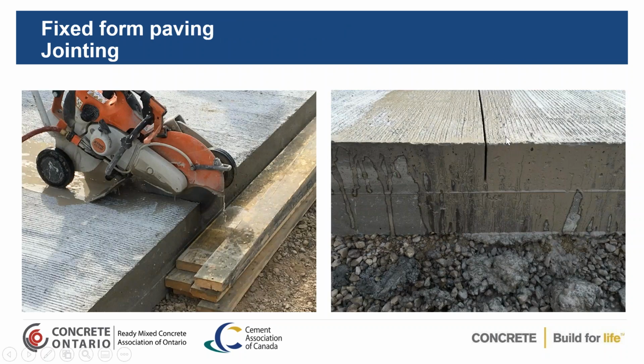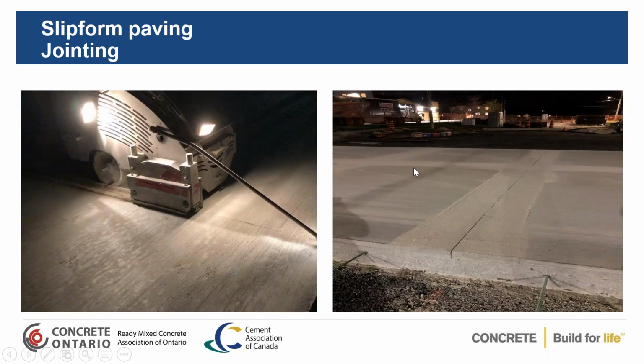So you see the cutting, and it's a great cut here. So your concrete's going to crack right here. So you're forcing the crack to develop in the location that you want, directly over the dowel baskets that you've placed. Again, in slipform, same thing. You've saw cut your joints to ensure that you have good timing in that. You want to make sure, again, to see here the tie bars are spaced or skipped so that you don't have a locked up joint here.